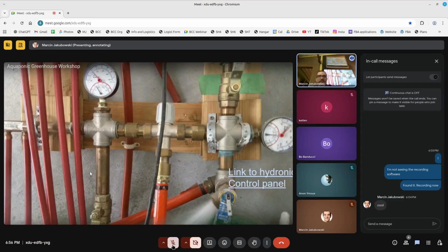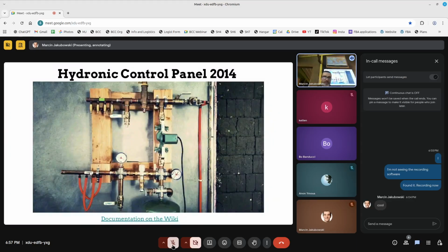But we've done hydronics like this here. Now, good news: you can do this with SharkBites these days. So right now, if I were to do this hydronic system again, I would actually use SharkBites, as long as you keep the temperature below 200 Fahrenheit, which is standard. The quick connect fittings can be used for hydronics heating as well. So that's really cool. This is a system from CDGO Home. We call this the Micro House 3. This is what we actually had: the hydronic system panel with an expansion tank and pump.